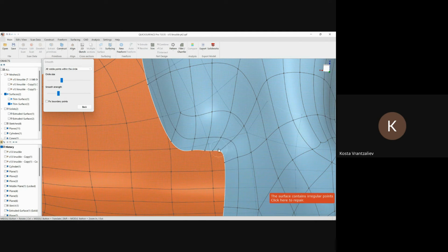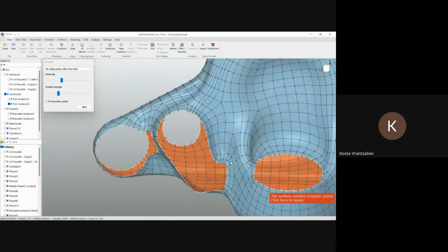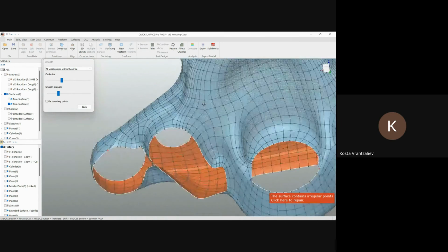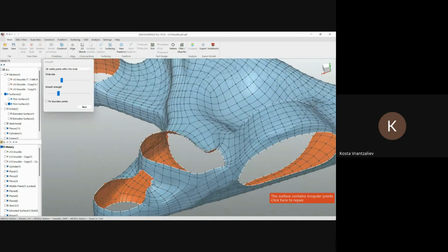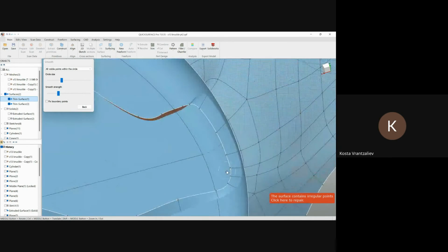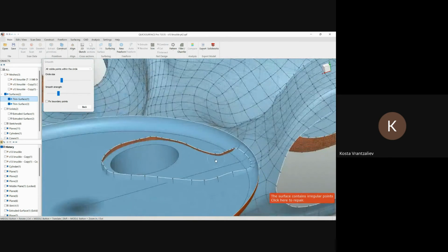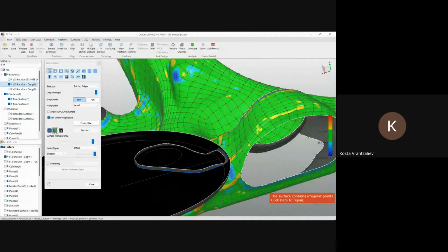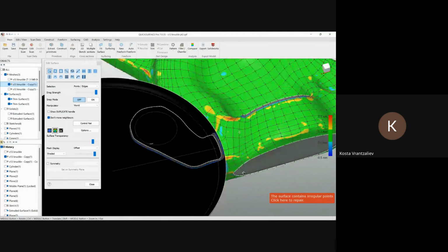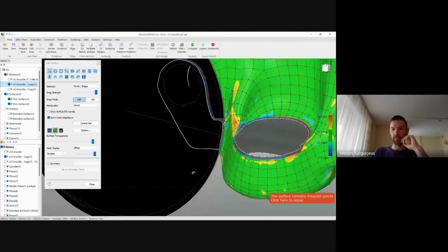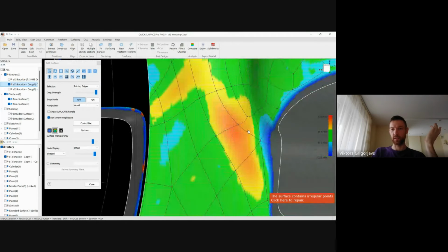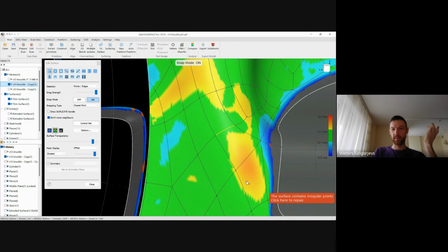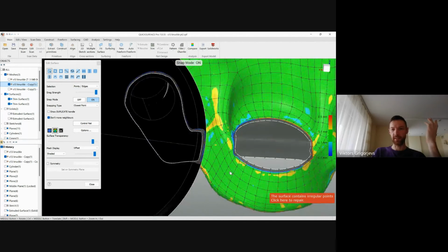In terms of accuracy here, for the freeform shapes, you probably don't care too much about how close it is to the underlying shape. So this should be good enough. As you can see here, it's really important that these vertices go outside of this prismatic shape, so the trim can work in the right way. If we're talking deviation-wise, it still looks good. Okay, first we can come over here and bring it to snap mode and just snap these vertices back. If it's that crucial for us, these places, it's not a big deal.